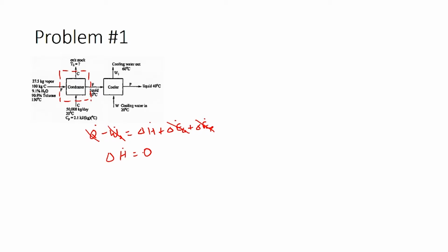So, now that you have delta H dot equals 0, we can write the expansion for H dot and identify the value for the temperature. So, here you also have only constants given as Cp values, which means you would not have a very complex polynomial which we used to end up with when we calculate temperature. So, usually we would have a third order or a fourth order polynomial which would be difficult to solve. Here it would be a simple linear equation which can be solved. So, let us try to do that. So, for doing that we first need to identify the reference states so that we can build the enthalpy table. So, let us look at what could be the reference states. So, here we are not going to be using any enthalpy table as such like steam tables or anything.